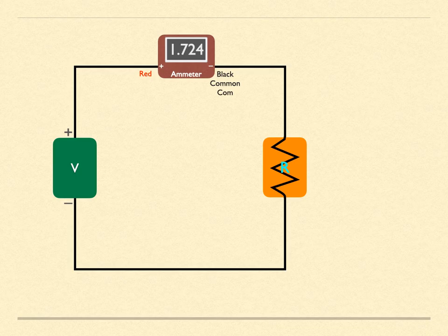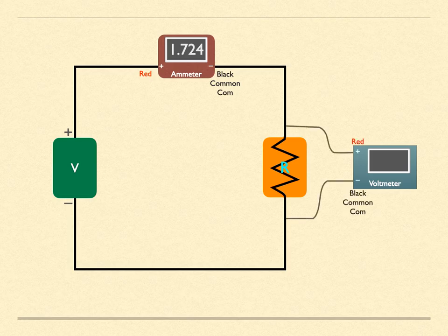Switch around the terminals. A voltmeter is a high impedance device. It too is designed to minimally disturb the circuit it is analyzing. While an ammeter might have an internal resistance of 1 ohm, a voltmeter might have an internal resistance of 10^12 ohms or even higher. Every part of the circuit that has a non-zero resistance will show a drop in the potential across it. As with the ammeter, connect the positive terminal to the positive side of the circuit, similarly with the negative terminal. They are again usually colored red and black respectively, with the negative terminal also labeled the common terminal. When connected correctly, you will measure a positive voltage. If negative, you have it backwards.